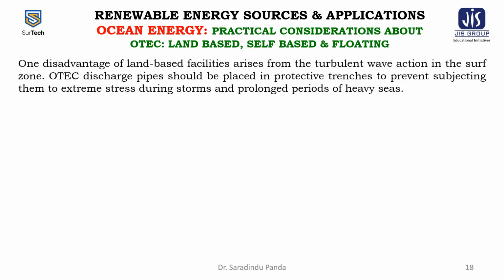One disadvantage of the land-based facilities arises from the turbulent wave action in the surf zone. The OTEC discharge pipes should be placed in protective trenches to prevent subjecting them to extreme stress during the storms and prolonged periods of heavy seas.